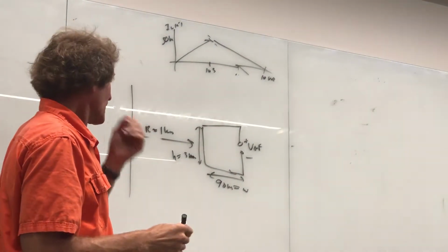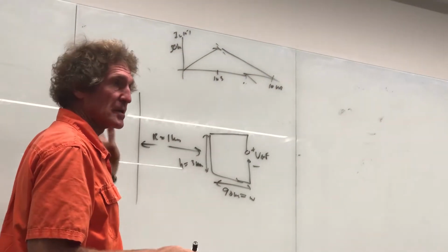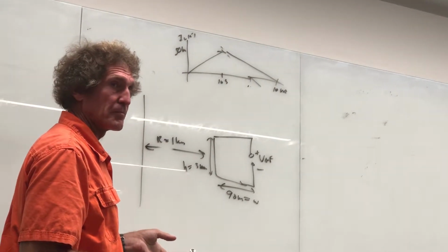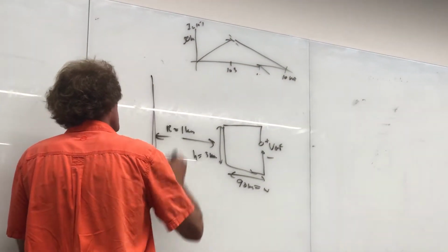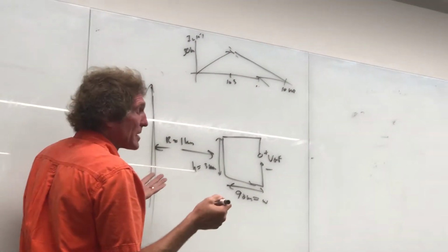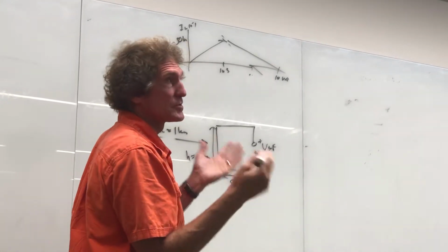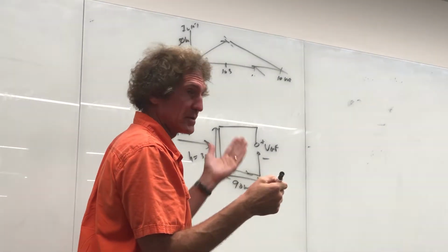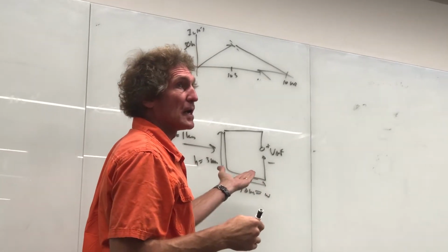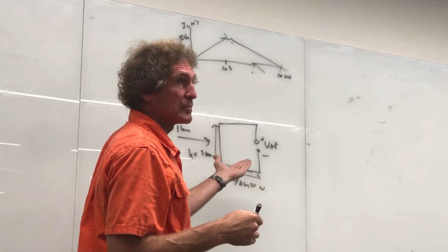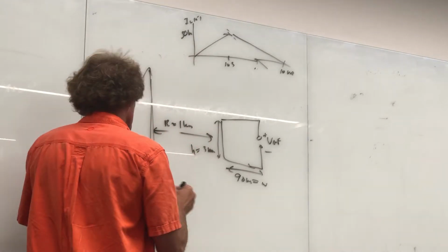All right. Well, this is the classic. Is the lightning current assumed infinitely long? Yeah, it says a very long wire. This is the standard one where we could get the mutual inductance and just use M times di dt for the induced voltage, because mutual inductance times time-varying current gives you the induced voltage. But we can go through it from scratch too.